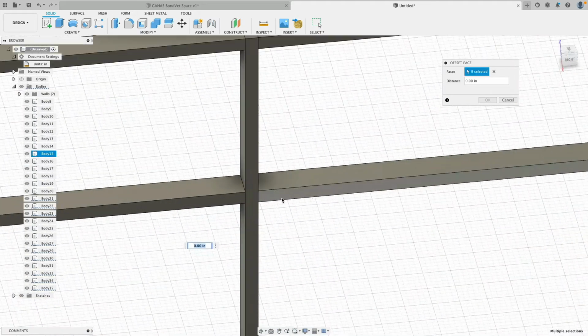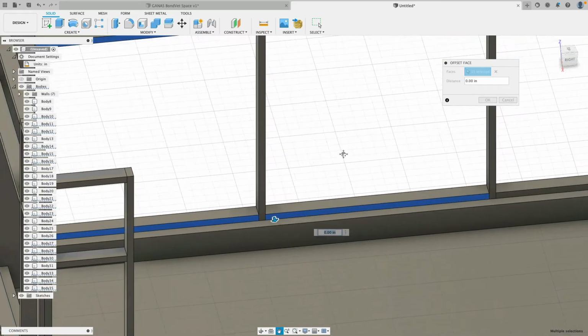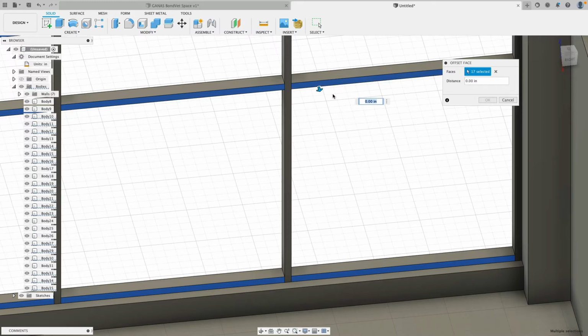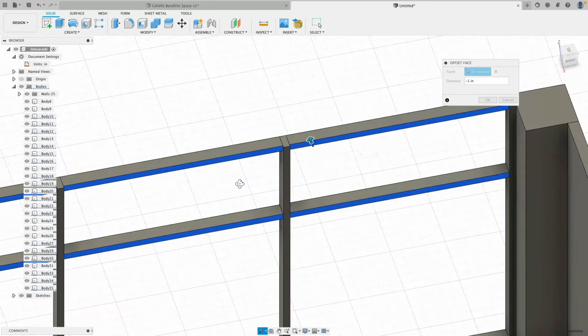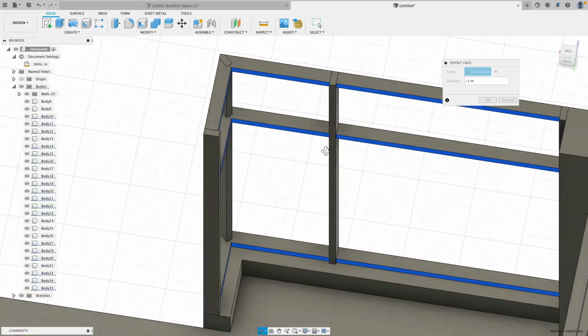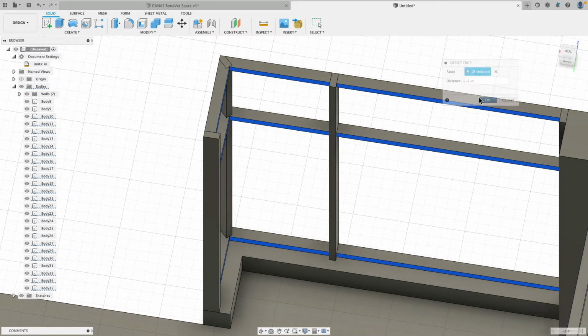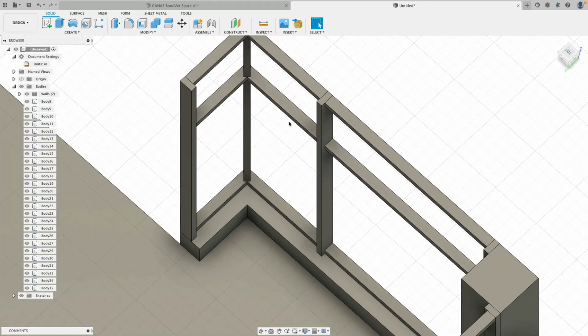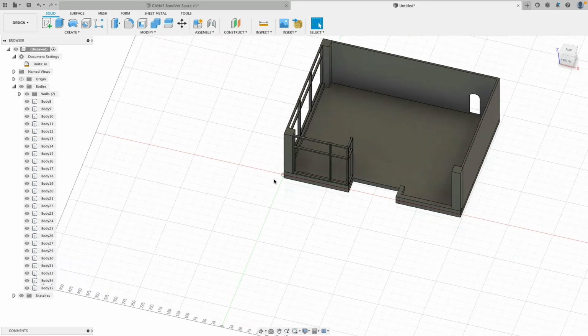Okay. And then same here. Do not select an edge because then you will round an edge. We only want to move these edges. Inwards -1. Let's see how this looks. Then there we can get a small overlap. If we say -2, then actually these corners are flush. Okay, that's what I found actually in the manufacturing document for the sample piece I had. This is 7 inches for the vertical and 5 inches for the horizontal pieces. Yeah, pretty cool, no? Yeah, I think so too.